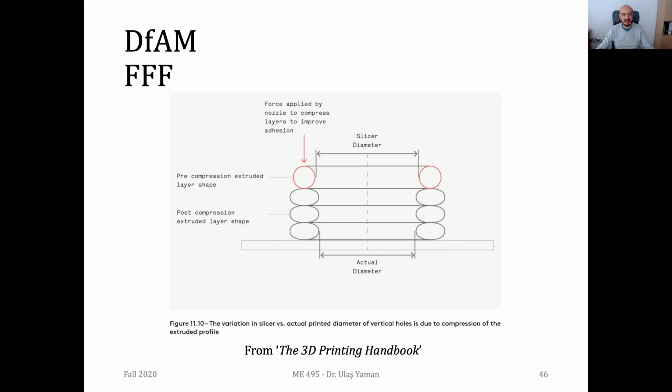And for that purpose, I think you all know we use kind of a brim. We extrude extra material around the part, especially in the initial layer, so that its contact area with the table is more than the original case. But it's not about shrinkage. It's warpage. And it's due to the thermal stresses developing at the specific corner, and this happens usually on the longer pieces. But yes, you're right, this is an important issue in triple F and also in other additive manufacturing technologies.